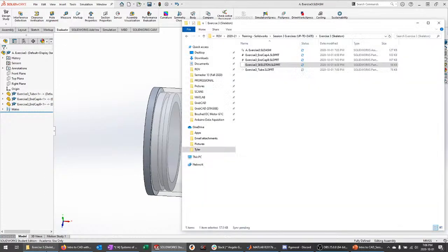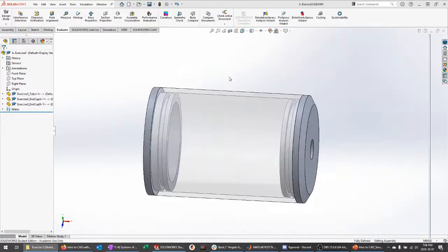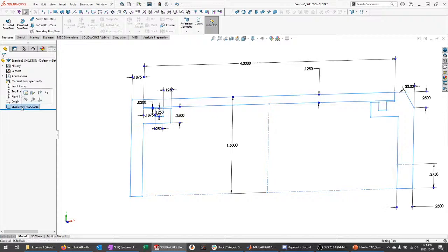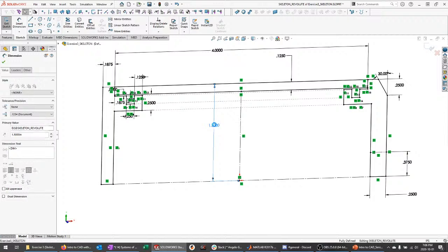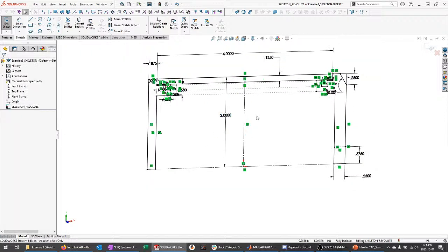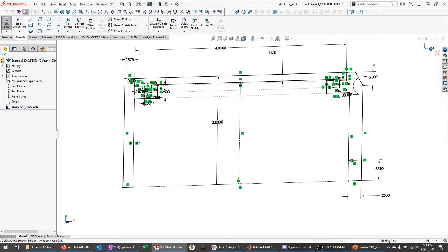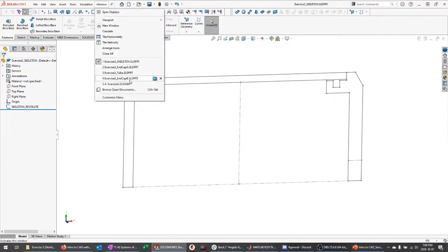Or, because we have skeletonized them, we can just go ahead and open up the skeleton. And by the way, there is no particular need to insert the skeleton as a separate part in the assembly. We can go ahead and open up the skeleton again. Going to edit this main driving sketch, and we said we wanted a 4-inch diameter tube, so I'm going to change this radius here from 1.5 to 2 inches.